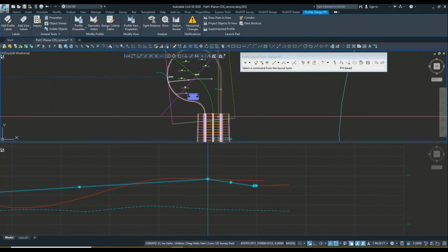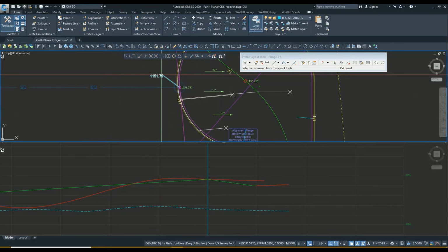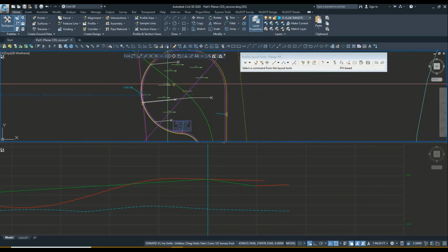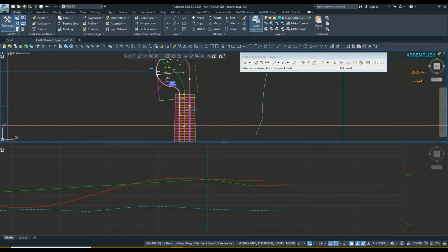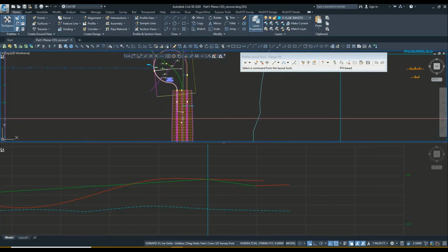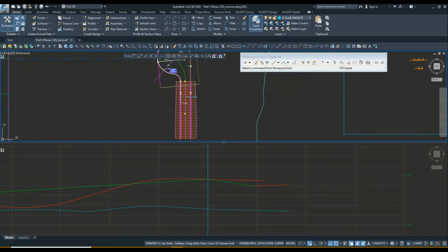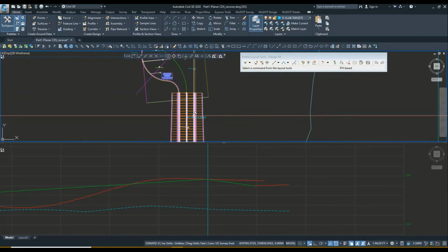And there's a couple of ways we can fix that. Either we can adjust this elevation, go lower. Maybe at this point you realize that 3% is maybe not the correct choice, or maybe we want to increase the elevation of this profile along the throat of the cul-de-sac. Maybe the cross slope might need to change a little bit from having a 2% going this way, maybe something a little bit higher.